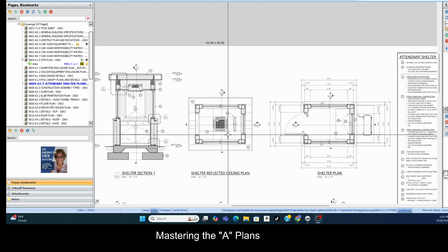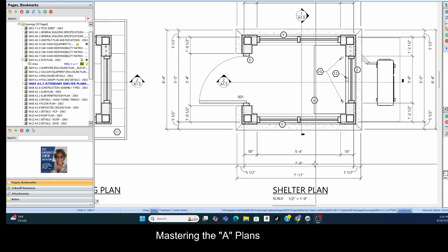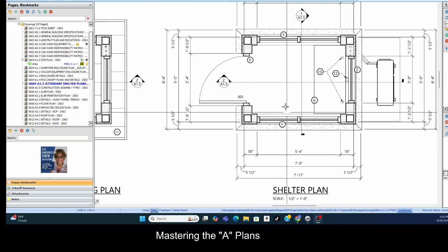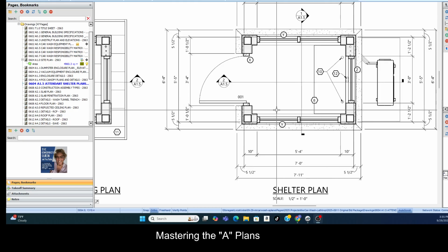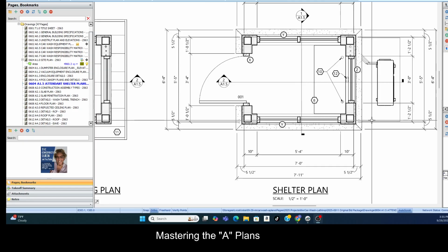And from a plan view in terms of framing, yes, we can determine how many linear feet. And again, if the opening is less than 16 feet, we're just going to include that in our opening. We're not going to deduct the openings. You can for waste or whatever if you need, just for your personal information. You can, but you don't need to. So the shelter plan is giving us instruction on how these walls are built.